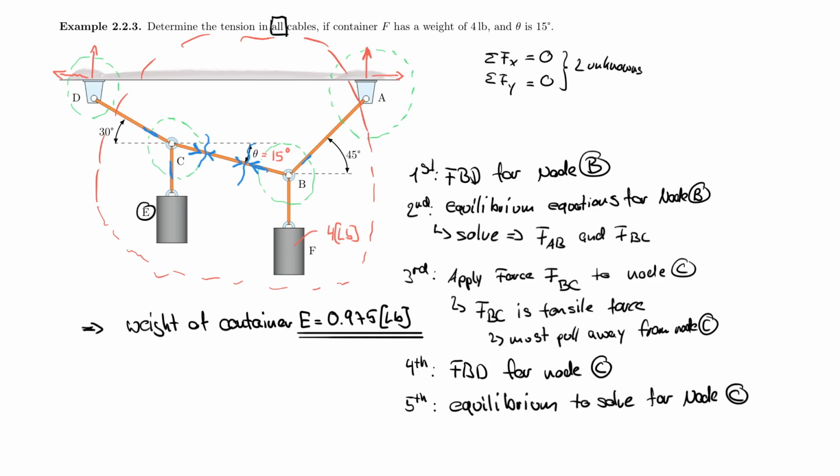So if you apply the 4 pounds down here, and then the 0.975, then you should find that the sum of your forces that are released here, which is going up, and here, which is going up, that those two forces, and maybe I should give them a different color, let me make them orange here for you, this plus this, of course, needs to be 4.975 pounds.